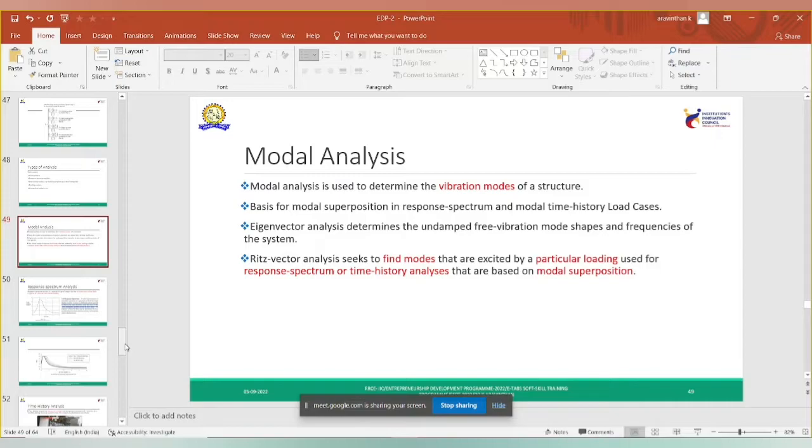And the next thing is the column. The column is not a load carrying member in dynamic analysis. It is a stiffness member. Column self weight will be ignored here and only the stiffness property of the column is taken. When you are doing static analysis, you deal with Young's modulus, the modulus of elasticity, as the major factor. But in dynamic analysis, the stiffness is very important for a column, and also the damping ratio.